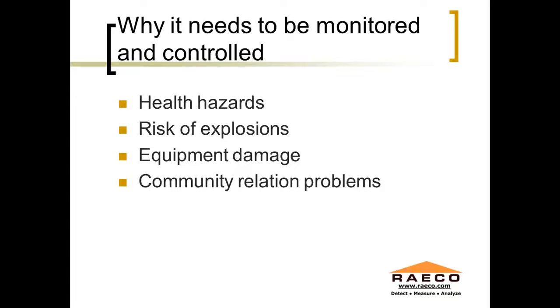Some of the reasons why we need to monitor and control for dust. Number one, of course, is health hazards. Short-term health hazards from exposure to aerosols could be eye, nose, throat irritation, runny nose, sore throat, etc. This could be typical conditions reported for indoor air quality studies, or maybe offices adjacent to a manufacturing plant. Those are short-term things, not chronic, but certainly things to be concerned about.